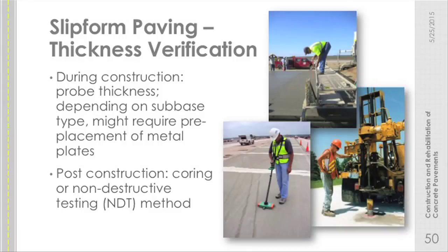For slip-form paving, our thickness verification, generally we will use someone on a bridge like this, an inspector, who just probes down into the pavement, wipes off the rod, waits till the next time, probes down, measures how deep it is. That's the easiest way to do it.